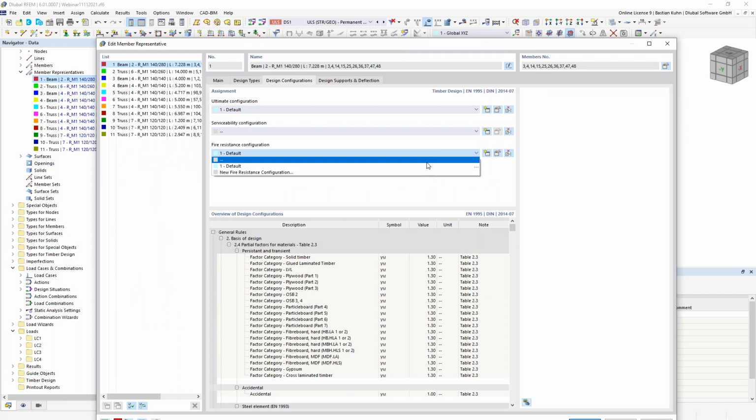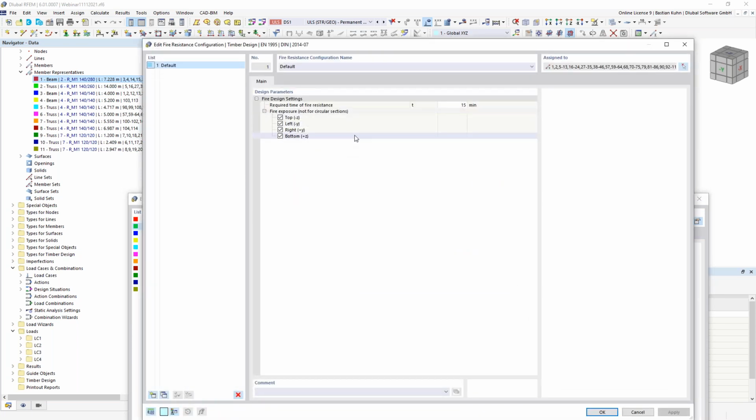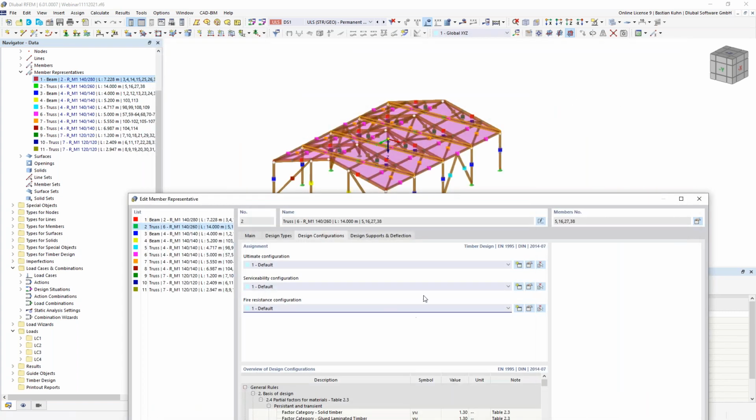And fire resistance as well. I will get to that point when I take a look at the other elements. And that's right now, because the bottom girder is probably exposed to fire, and I want to expose it to fire for 30 minutes. And I say, okay, 3 sides of the structure are exposed to fire, and that's enough for me.